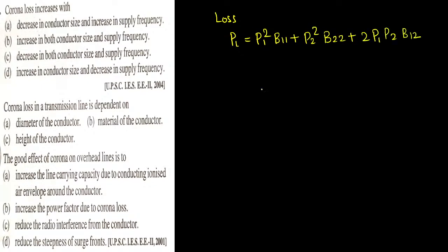Actually, I forgot. In our last class, when we were discussing economic dispatch with the losses, I was writing the expression for PL, right? What we had written was P1 square into B11 plus P2 square into B22 plus 2 times P1 P2 into B12. After writing this expression, in a problem we were trying to differentiate dPL with respect to